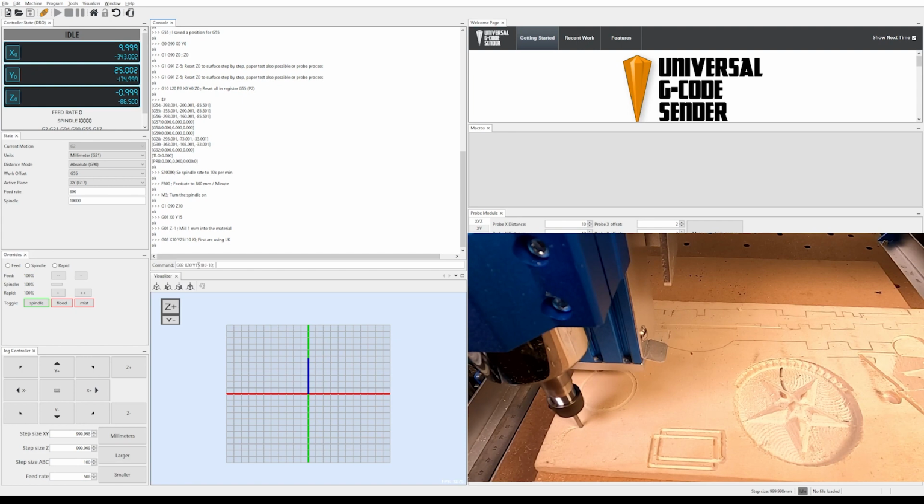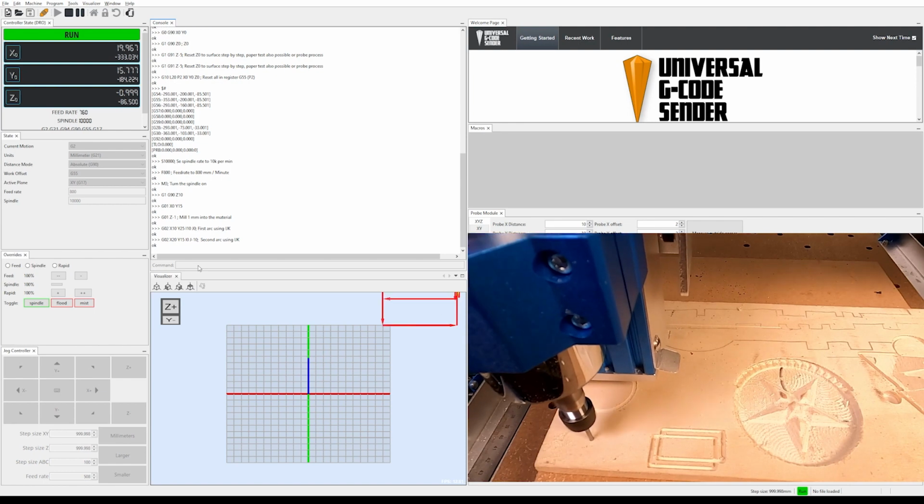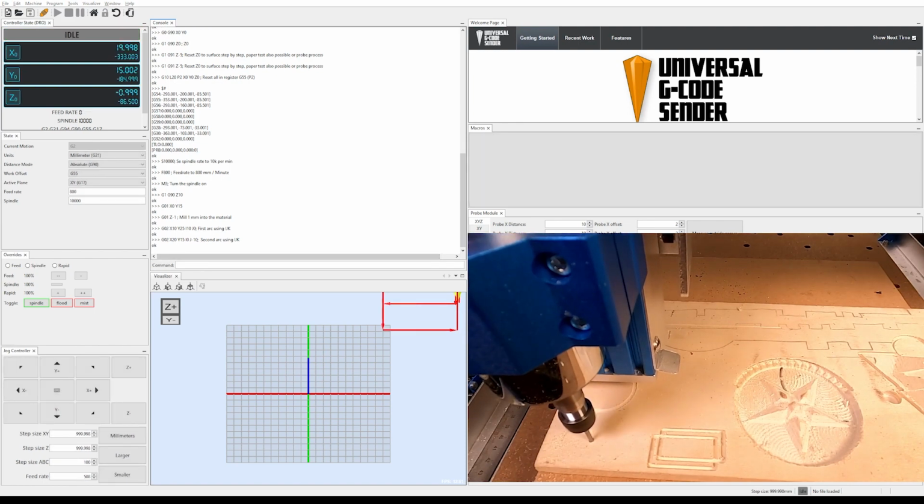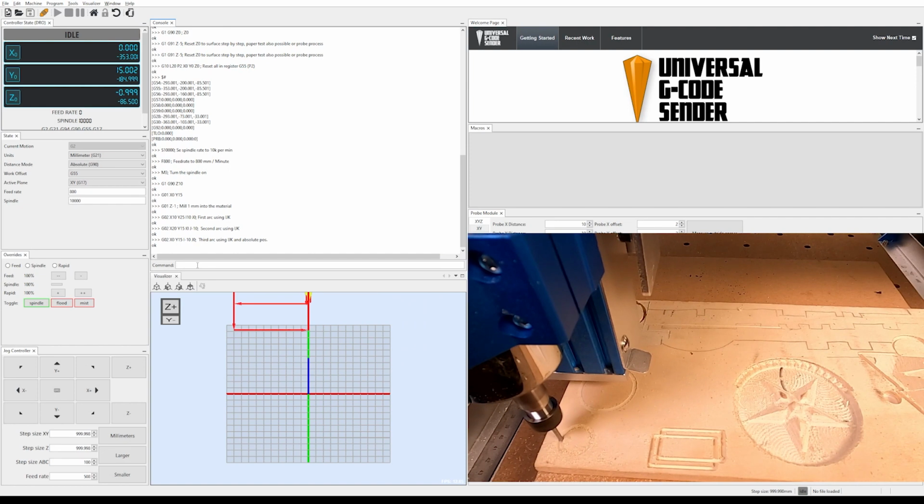Once it reaches the endpoint, it will stop and we can proceed to the next position, which is X20 Y15, and again it mills an arc with 45 degrees. Finally, we will use another G02 command to mill the last arc with 180 degrees back to the starting position, which is X0 Y15. The CNC machine will move in a clockwise direction again, milling the arc until it reaches the endpoint at X0 Y15.